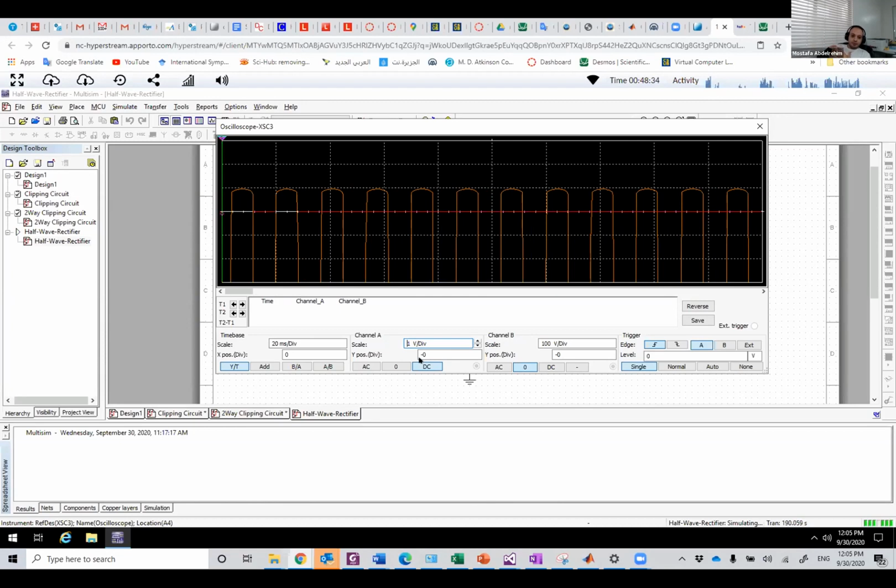Basically, remember, we are dealing with the constant voltage model. In the constant voltage model, we assume that whenever the diode becomes on, it's 0.7. Although that's not exactly the case. We saw there is a change in the voltage as well, but the change in the voltage is really, really, really small. It was between 0.6 and 0.8.